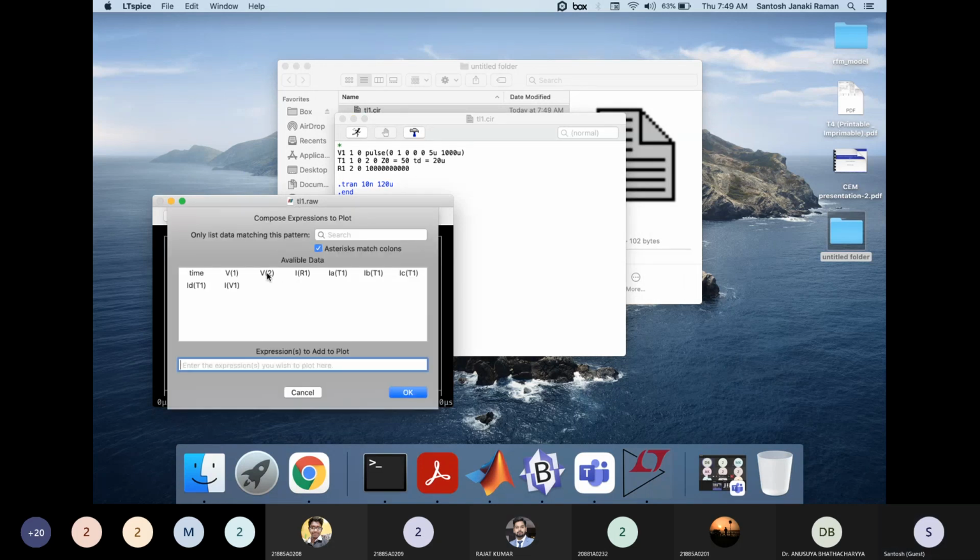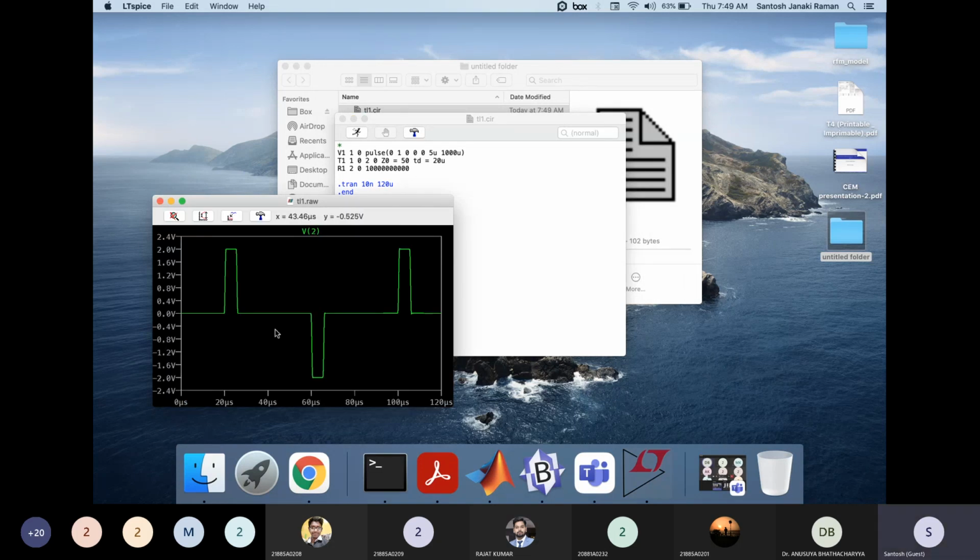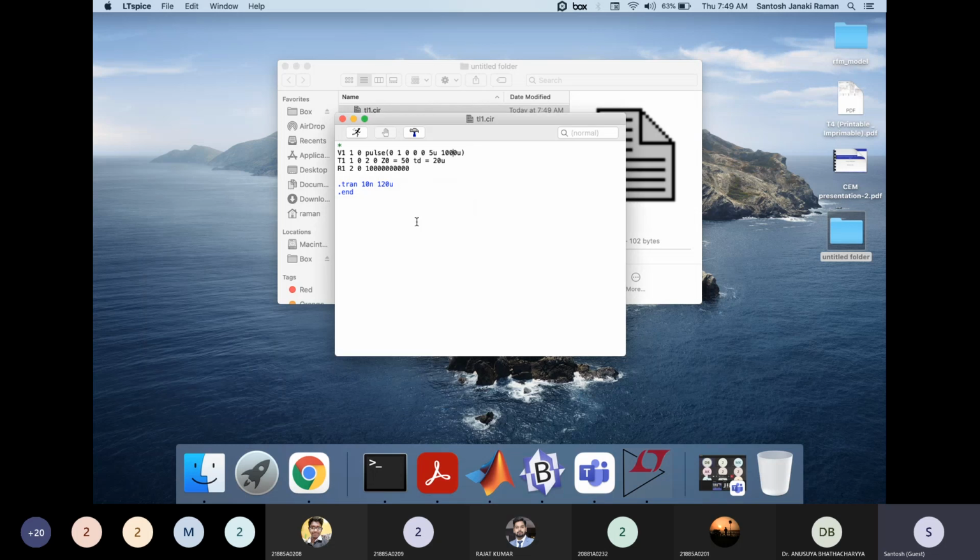For example, you measure the time between the subsequent reflections, and then you will know at exactly what point in the transmission line you have a breakage. This is called time domain reflectometry. So you can measure the time delay between the voltage source that goes and comes back, and use that delay to find exactly where you have a fault. Correct? This is something that's commonly used in industry. This reflection phenomenon is commonly used in industry.